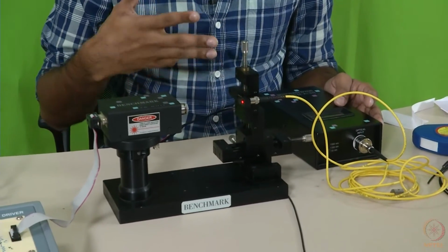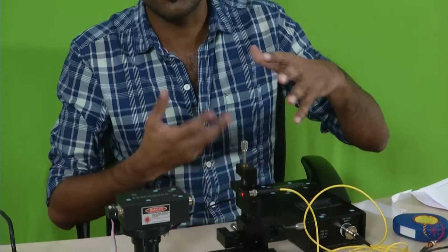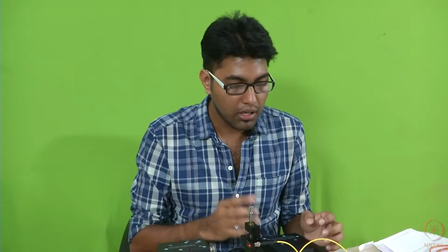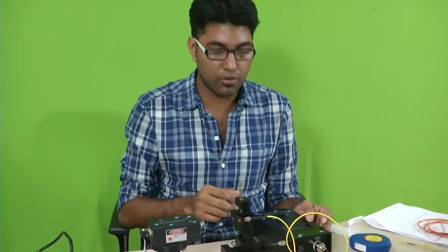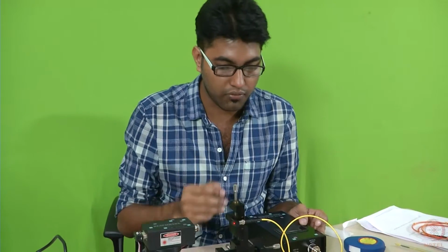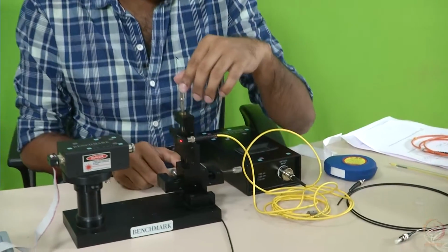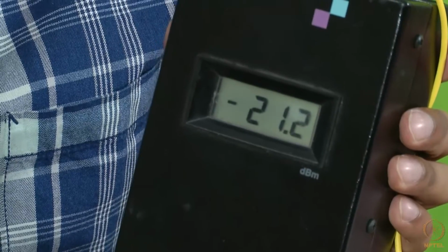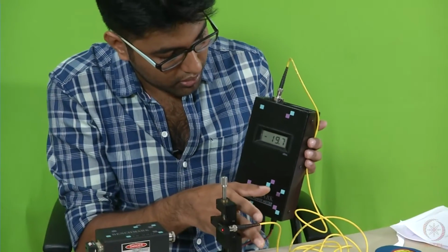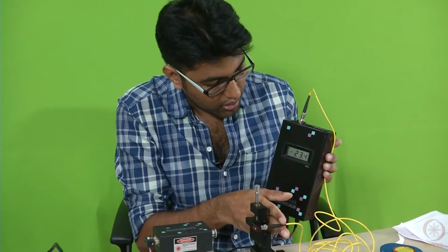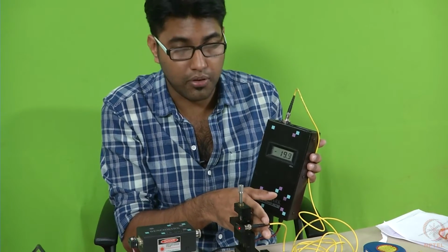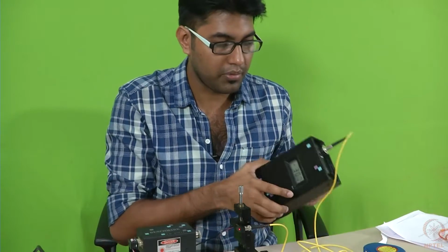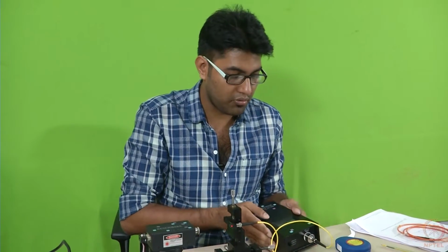Now that is because probably the alignment of the other fiber was not that good, and it was not mandatory for the fiber to have that good an alignment. In here the fiber needs to be coupled very properly with the optical source, so the light should go in. Now we had to do some fine tuning so as to get maximum power into this optical fiber. So again you had to do some XYZ translation. As you can see, with great difficulty we are able to get around 18-19 dB of power here. So that's how you couple light into the few mode fiber.